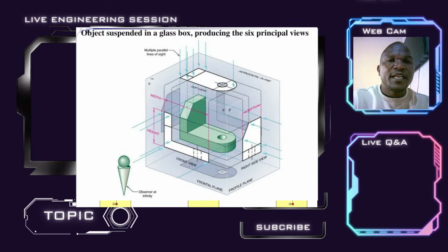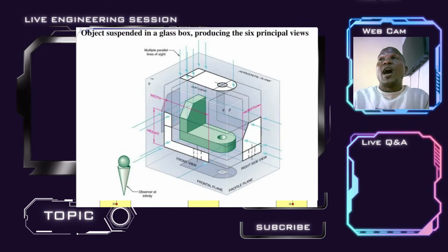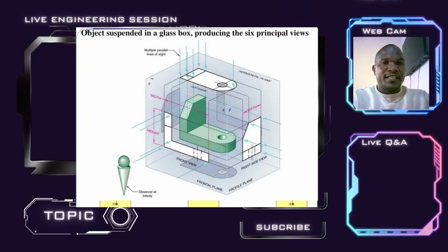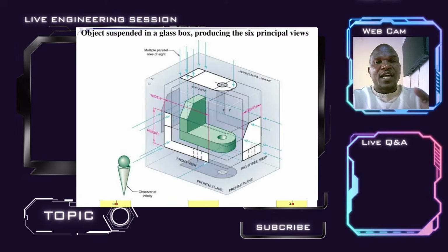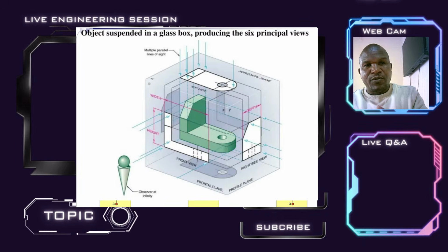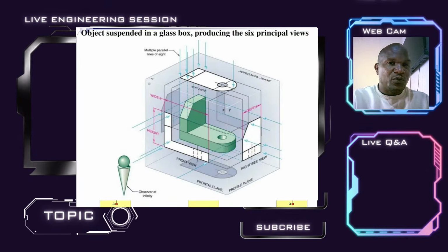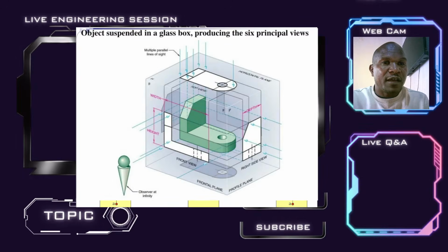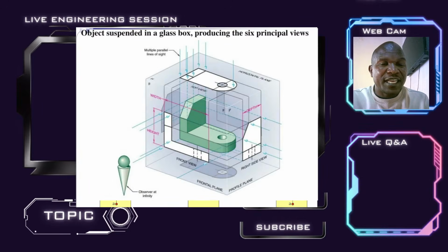The profile plane is either on the right side or the rear side, which is now the side where you've drawn the side view, or the rear side view, which is reflected. Again, I say reflected. As you can see, there's a reflection of the same view darkened in gray on the rear side.